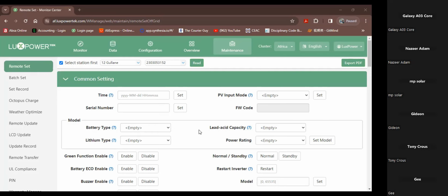So what happens if it is in the middle of winter, the ambient temperature is 5 degrees outside, you're in De Aar or you're in Bloemfontein, and the air temperature is very low, but it's a crisp, clear day. So in other words, we've got the perfect conditions for spiking: low ambient temperature, the panels are angled perfectly, and it's a crystal clear day. And then your solar irradiance is fantastic, and now all of a sudden your voltage spikes up and it exceeds the range of the MPPT.